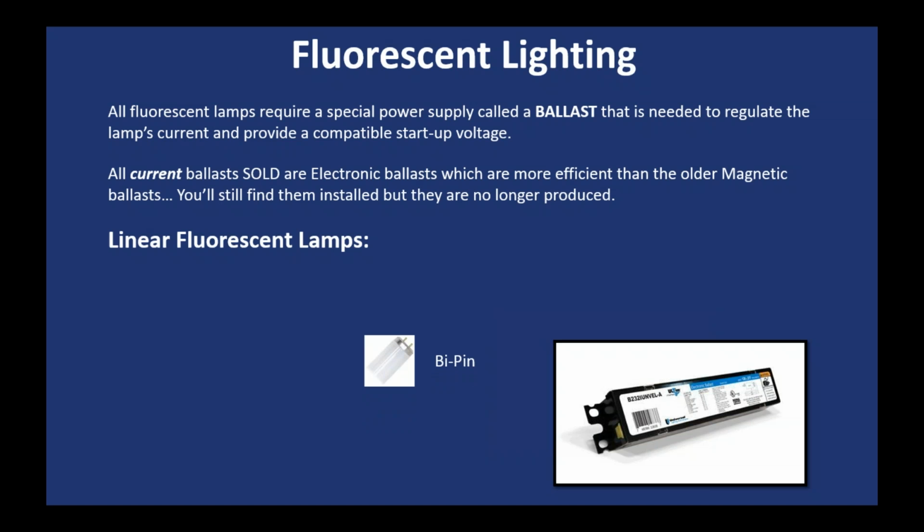Linear fluorescent lamps, what we're looking at. Let's go over the types of those. Bipin lamps for your typical 4-foot fluorescent lamp that's in most office buildings, your dentist office, those kind of places. The 2-pin, that's one of the most common things that are out there. When you see the long lamps, the 8-foot lamps, most of those, the majority on the inside and indoors, will be single pin lamps like you see listed on that. And when you go outdoors, typically what you're going to see, whether it's a 4-foot, an 8-foot, or in refrigerator lighting, you get into the F72s, you get into a 5 or a 6-foot bulb.